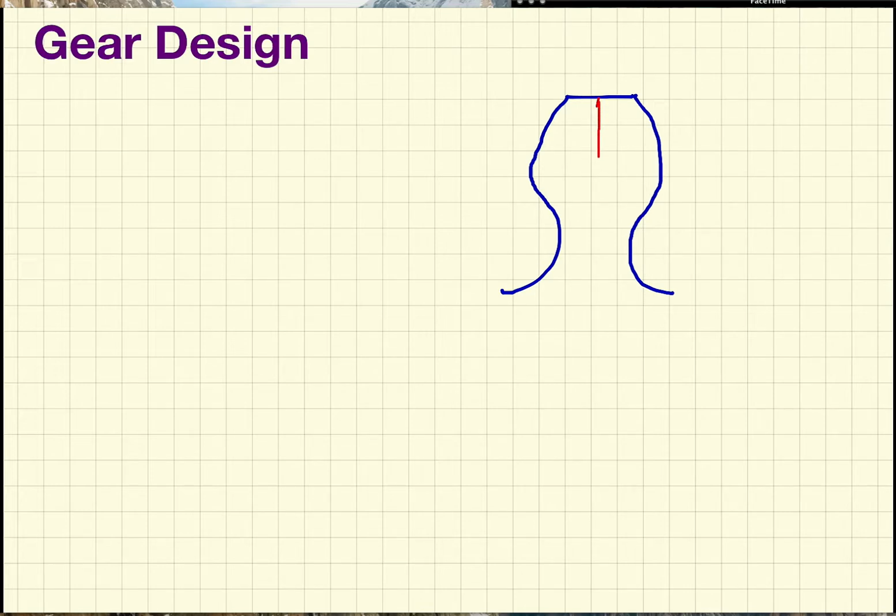We will consider that we have a center line like here, and to that center line we can make a tangent to the root of the gear, and from the tangent point to the corresponding tangent point, this will be the width of the gear tooth. And if we take a normal here, this normal will meet at a distance x below the root of the gear.